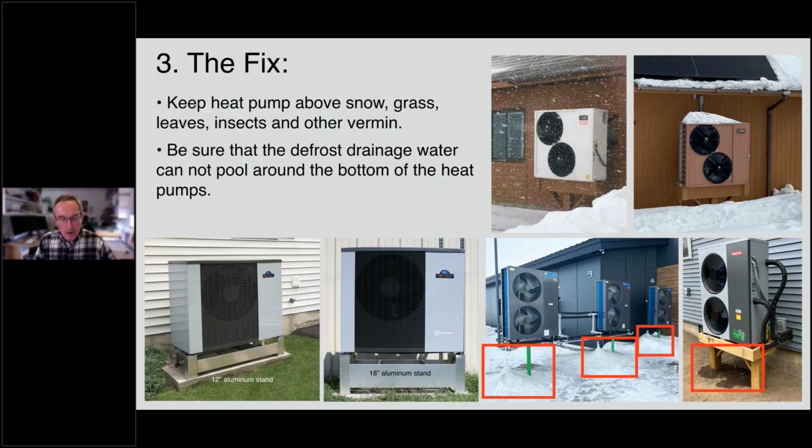That water that drains out of the unit during defrost will flow out maybe an inch or two and it'll freeze. And I've actually seen this happen. It'll create what I'll call an ice bathtub around the base of the heat pump. And then as more defrost water accumulates, it can actually come up and freeze on the coil. So we want to get those units up and make sure that there's nothing that's inhibiting the water drainage from the bottom.